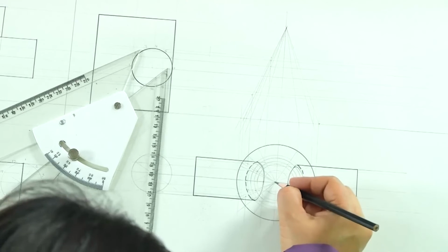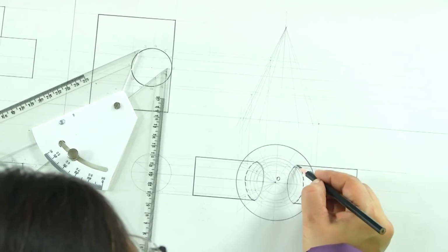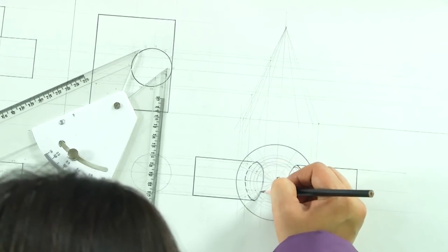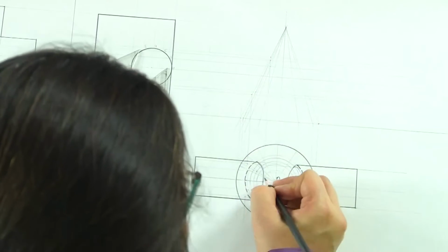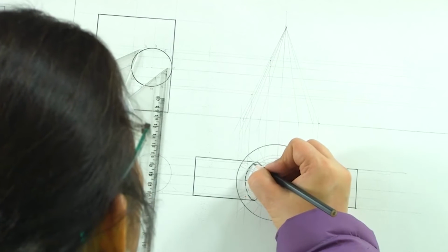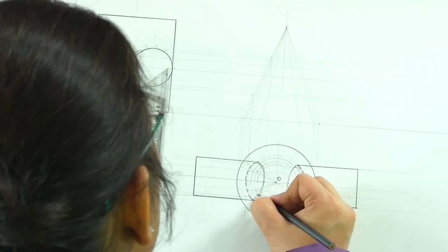So, in the top view, what we will see is the apex being intact, the cone being cut in a very odd shaped curve here, because from the top it is smaller, and as it goes to the bottom part it is bigger, and towards the top it tapers.